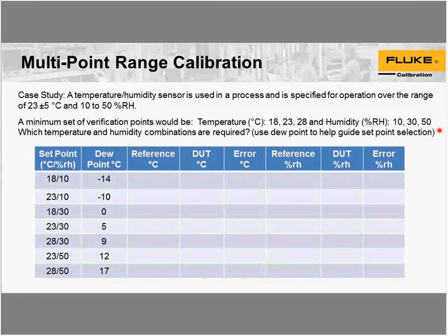Okay, someone is reporting the idea that when we mentioned the two pressure chamber, it's important to make sure that you use multiple temperature probes inside of it to know what the temperature is exactly at the point where your sensor is located. So we appreciate that.